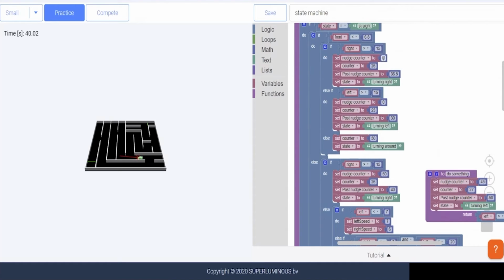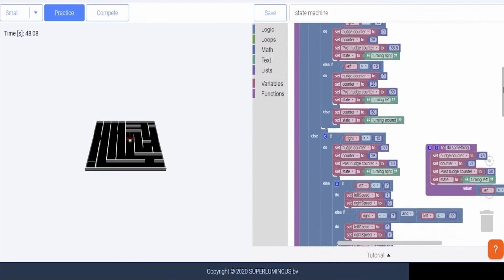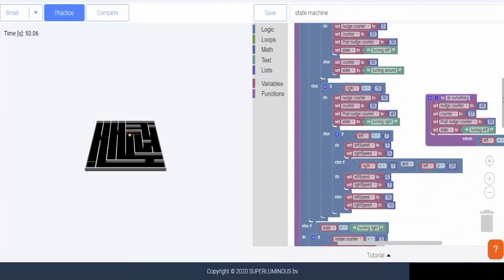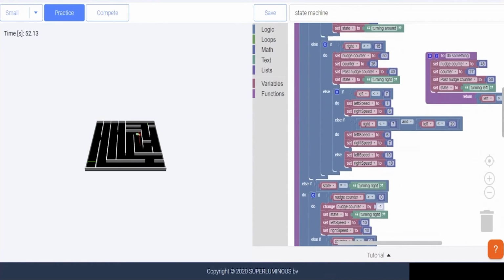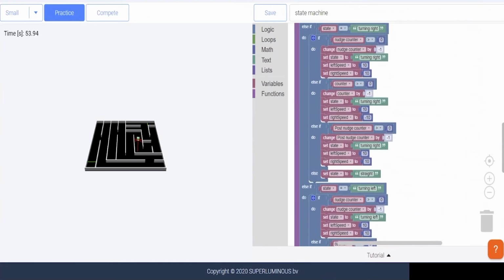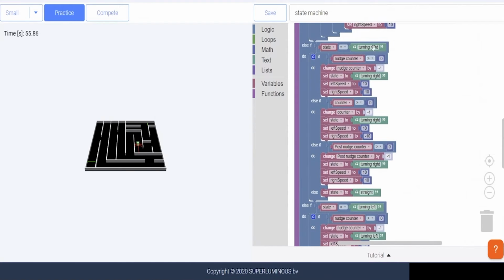So your nudge counter is 0. Okay, because otherwise you're going to see a wall, you're going to drive forward a little bit into the wall, and then you're going to try and turn around on the spot. So all we do is we add in these nudge counters, and then when we get to our piece of code, to our turning state, here now we have turning right. Okay, turning right, we first check our nudge counter. Okay, if our nudge counter is greater than 0, we're going to keep nudging, so we're going to go forward, right? So we're just going forwards here.